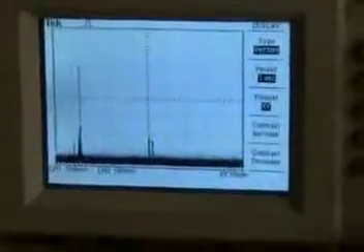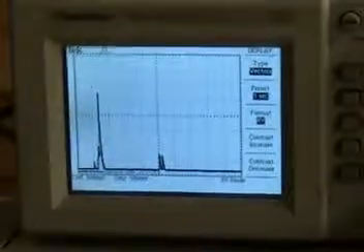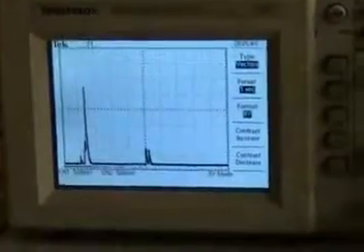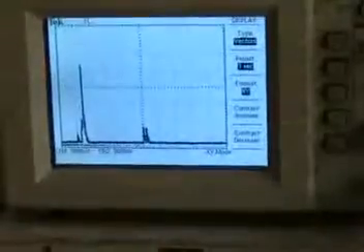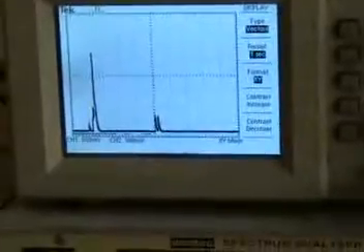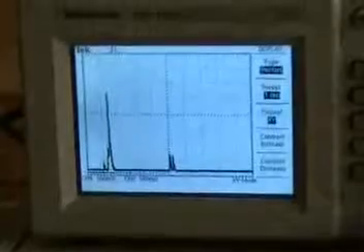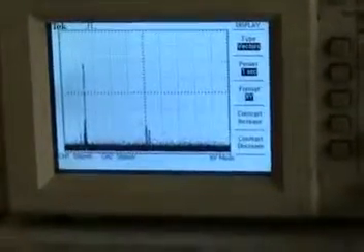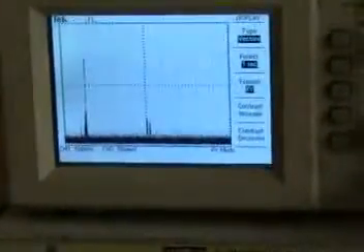So as you can see, if I switch on the video filter, the level displayed will not be correct because it becomes an uncalibrated input, but the noise has been reduced with the help of this video filter. So now you can see that the signal is displayed better, but it is in uncalibrated mode. Here the noise has not been cancelled, so the spectrum is in calibrated mode.